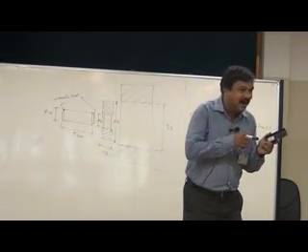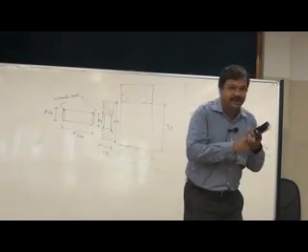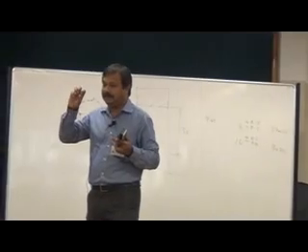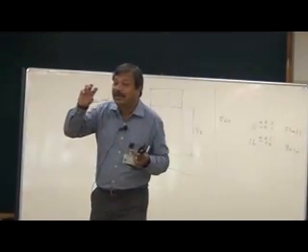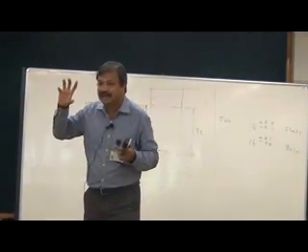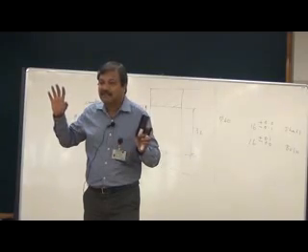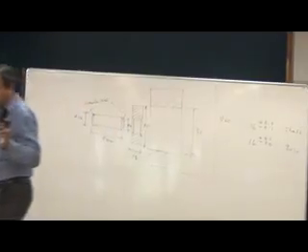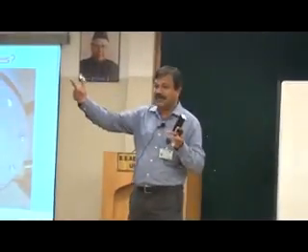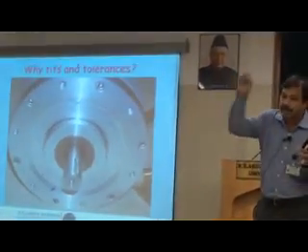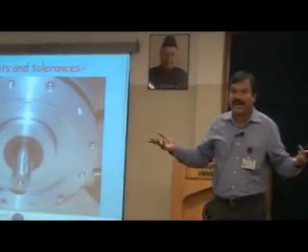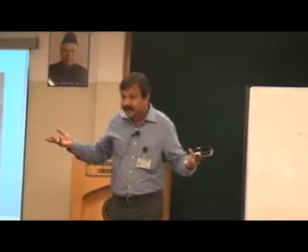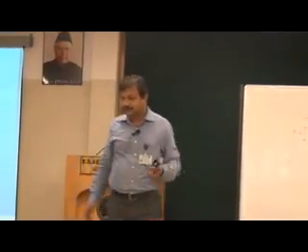As a design engineer, I have made the shaft diameter slightly smaller, the hole diameter slightly larger, and ensured that there is always a gap between the shaft and the hole. This gap will subsequently be filled with some lubricating oil. The shaft will be able to run very freely inside the bush.